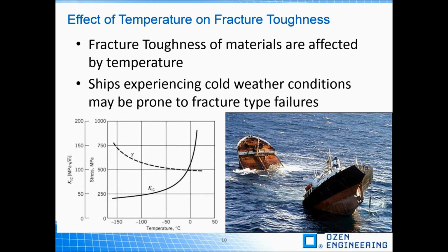And one of the factors in failure of Liberty ships was them being built with block welding, predominantly welded, as opposed to riveted hull construction, which allowed cracks to run for large distances unimpeded. So this is one of the design rules actually we have seen just a couple slides ago, by separating the fuselage into multiple sections. Just the quite opposite design was taken here, and it resulted in these catastrophic failures.